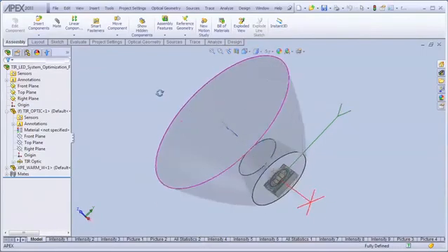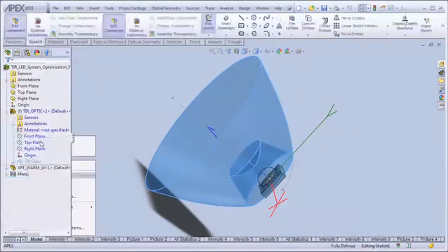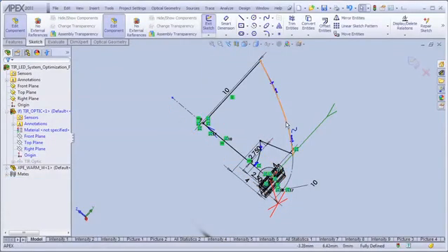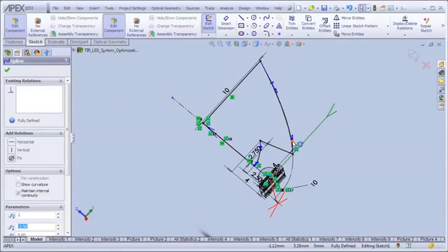Here is another example of a TIR reflector. The TIR reflector is composed of both reflecting and refracting surface elements. Apex's optimization allows you to control spline tangent radial directions and weightings, which in turn control the shape of curves, and changing these parameters allows you to change the curve shapes in order to meet your optimization goals.